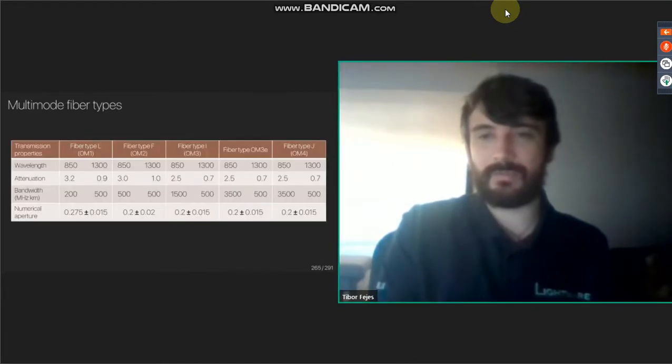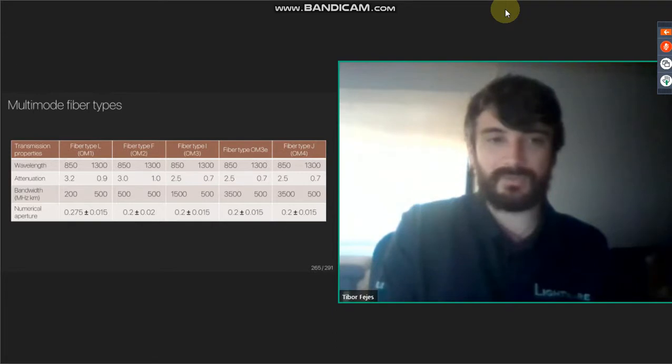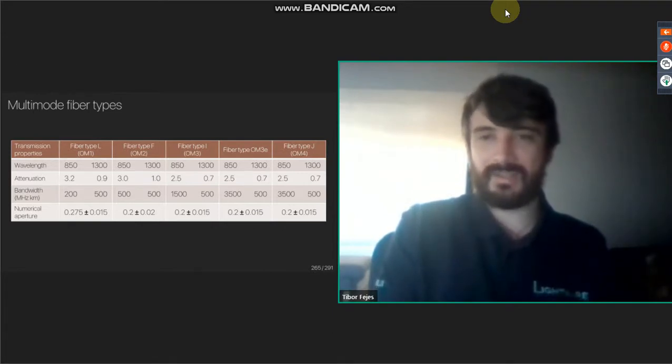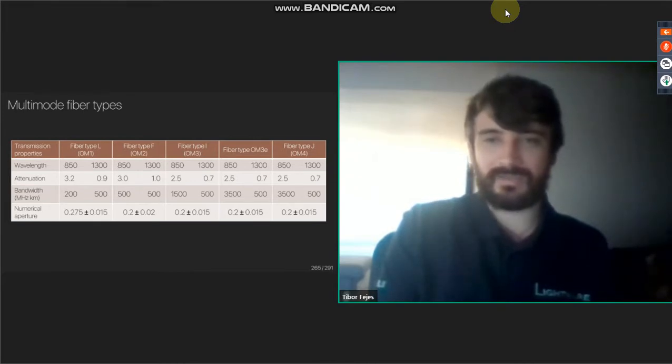So some of the numbers about optical fiber. The quality of the cable in multi-mode is determined by the OM number. In single mode, it's OS, and generally the higher the number, the better the quality of the cable and the longer the distance you can transmit.